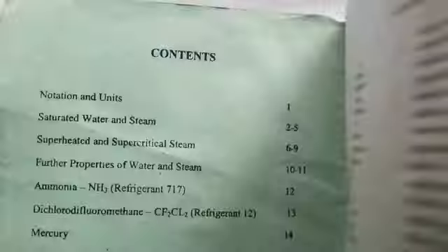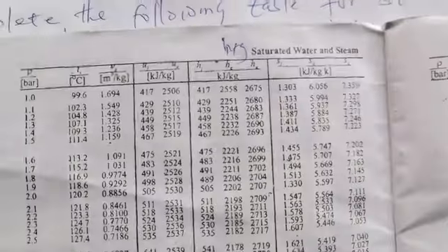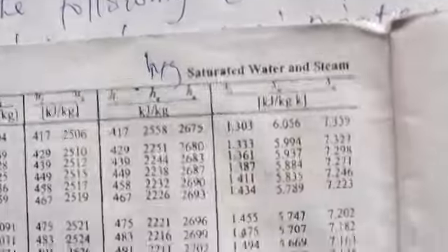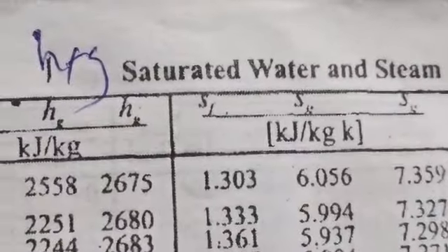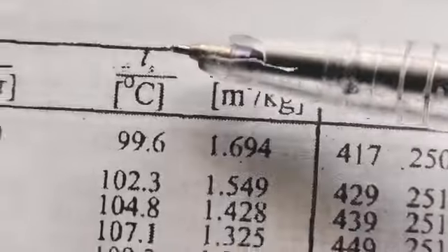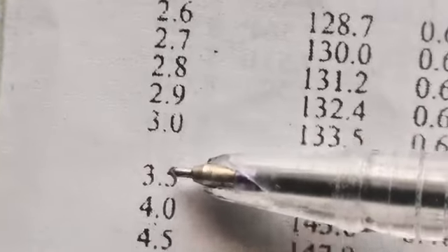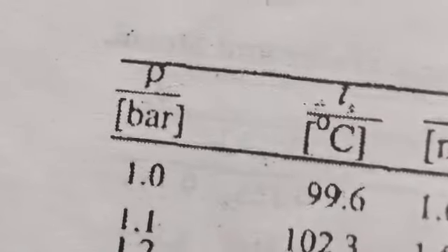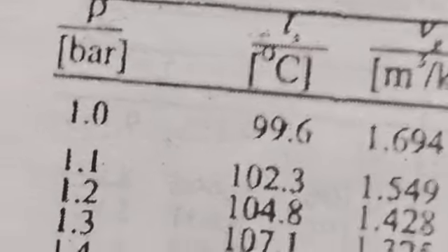Okay, so this is our steam table. Please go to saturated water and steam. Let me zoom it up a bit. All right, so this is saturated water and steam corresponding to the given pressure of 5 bar. This is the column for pressure. You trace out 5 bar. We're looking for the temperature corresponding to that point. Remember, after pressure, the next column is temperature in degrees Celsius, as can be seen. Okay, so locate temperature in degrees Celsius directly at 5 bar.